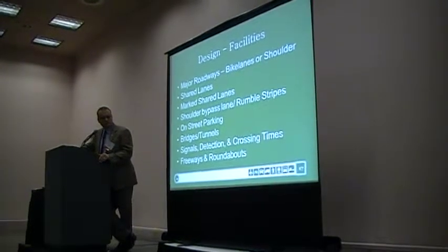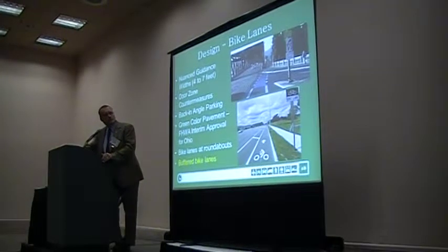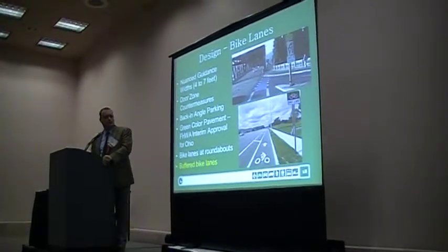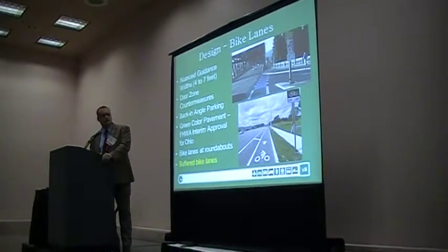Guidance on bridges, signals, freeways, roundabouts. Bike lanes, you'll find there's discussion of 4 to 7 feet, when to do it. Typically it's 5 foot.